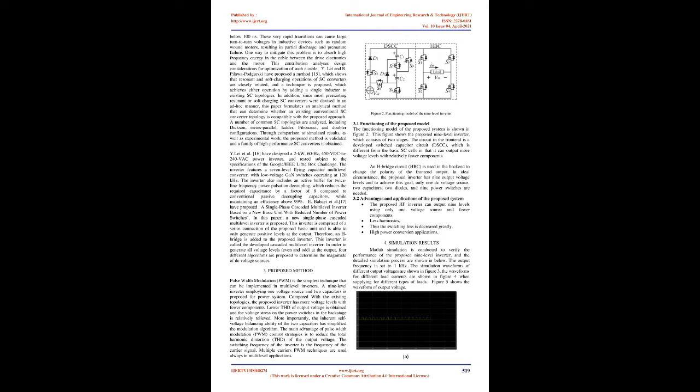Serban et al. have proposed a system for solar inverters. Solar plants based on single-stage conversion photovoltaic, PV, inverters have gained popularity due to their simplicity, high efficiency, and cost-effectiveness. Existing PV plants mostly operate under 1000V and are subject to wide DC bus voltage variations due to the effect of PV cell temperature and the voltage of the maximum power point. This paper investigates 1500V solar inverters with a focus on DC bus voltage range extension capabilities through novel modulation and power devices utilization. A comparative analysis with the existing 1000V solar inverters is presented to illustrate the significant advantages of the wide DC bus range in 1500V systems.